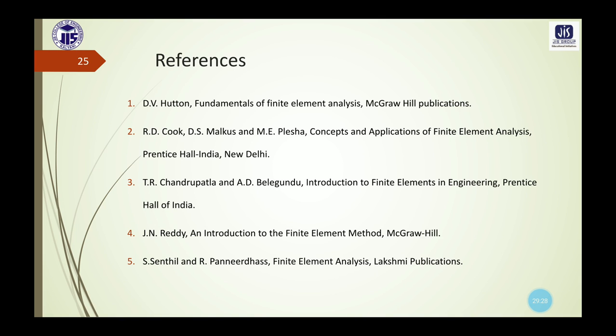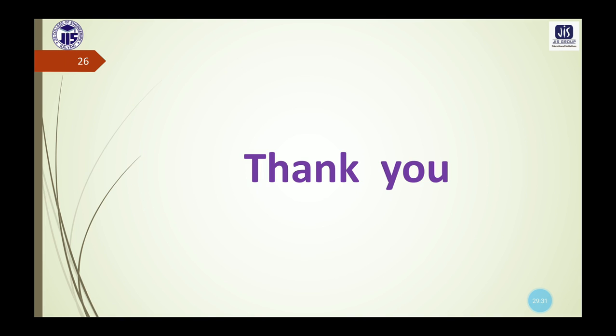So these are the 3 different numericals that we have discussed in this lecture, where we have calculated the Jacobian matrix, then the element stiffness matrix, then the stress strain relationship matrix. We have used the formula for the Jacobian matrix and the formulas of the shape functions, all these different formulas which are actually very complex. So a lot of practice is required to solve such numericals based on the quadrilateral element for this isoparametric element.